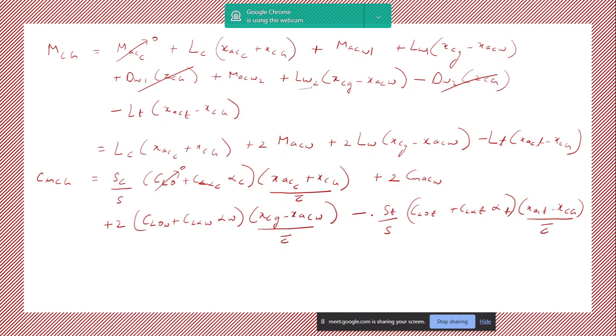Okay, here ideally there should also be an efficiency factor, that is V infinity dash square by V infinity square, because there's a downwash component associated with the wing that makes the effective velocity at the tail less than the velocity that the wing sees. Okay, so for this derivation we'll just neglect this, but that term should also be there. And our CL naught tail is again 0 because it's symmetric. Okay, so now let's just write this down completely.